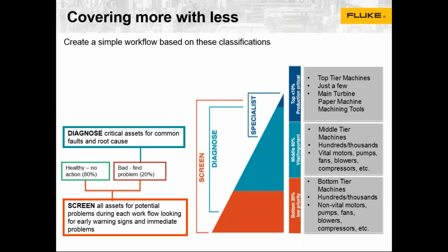A diagnostic tool is like your general practice doctor. Your general practice doctor is going to look for the most common problems. A diagnostic tool for rotating machinery would do the same thing. Our most common problems are easy to fix. For a rotating machine, the most common problems really boil down to 4: imbalance, misalignment, looseness, and bearings. That's about 90% of the problems with rotating machinery. And those are easy to repair.